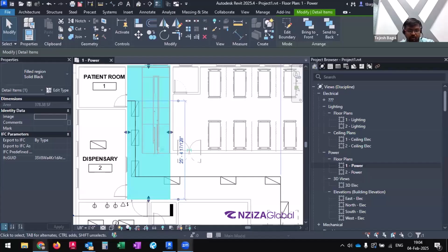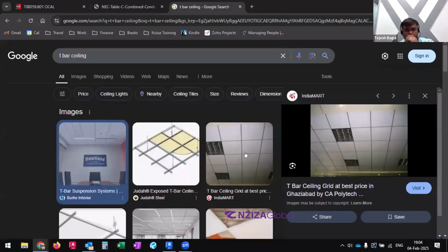So Tony, as I mentioned, the spacing between the lights will be dependent on the given grids that are available. So it is a joint collaboration between the electrical engineer or the lighting designer along with the architect to properly equally space it, right? So if I go back to the snippet that I had over here, as you see, they have repeated a pattern to make sure that the lighting fixture fits in one of the grids.